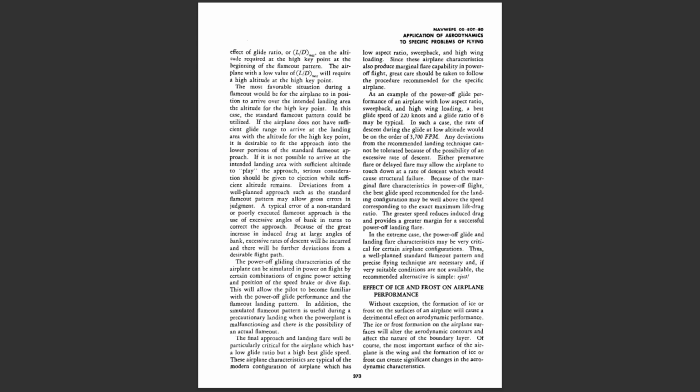Because of the marginal flare characteristics in power-off flight, the best glide speed recommended for the landing configuration may be well above the speed corresponding to the exact maximum lift-to-drag ratio. The greater speed reduces induced drag and provides a greater margin for a successful power-off landing flare.